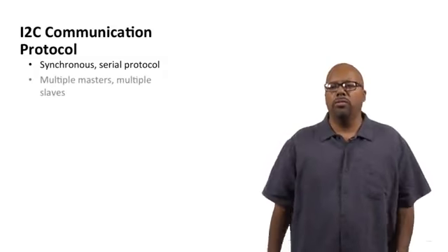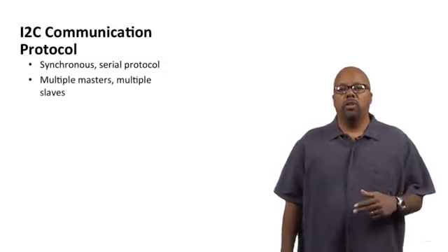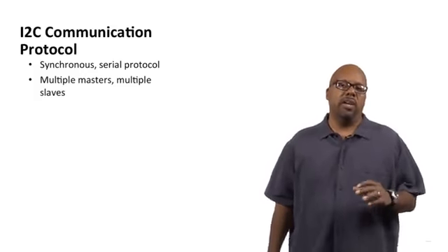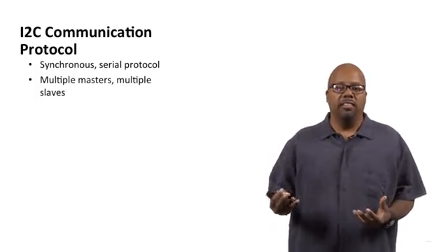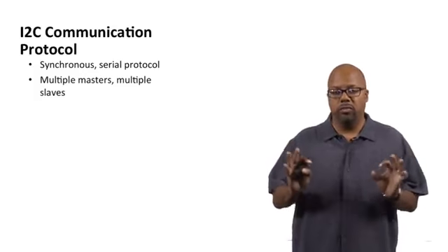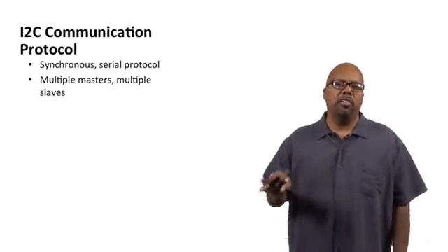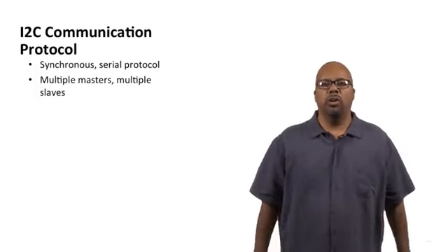It's a serial protocol. Multiple masters and multiple slaves. We're going to talk about this concept of master and slave. Basically, the master is the one who starts all the communications, and the slave is the one who waits for communications, roughly. And you can have multiple masters and multiple slaves in this particular bus protocol.